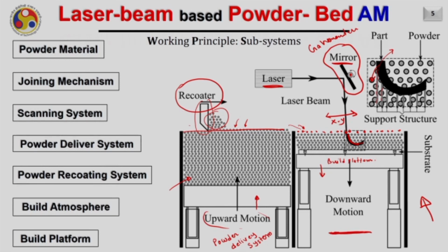And now during the cool down phase, assume that it is a large overhang, meaning there is no solid part under this, but there are powder particles. While scanning this powder layer on the top, definitely it will be supported from the bottom by the loose powder particles. They will not allow this layer to fall down.